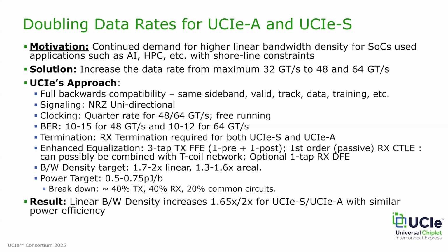We'll deploy enhanced equalization techniques to support the increased data rates. These are things like having a 3-tap transmitter feed forward equalizer, FFE, and that provides precise control over signal shaping. It minimizes the intersymbol interference. We also have a first order passive receiver side continuous time linear equalizer, CTLE, that optimizes the signal quality by compensating for any channel impairments that are there. We also have the provision for an optional one-tap receiver side decision feedback equalizer, DFE,